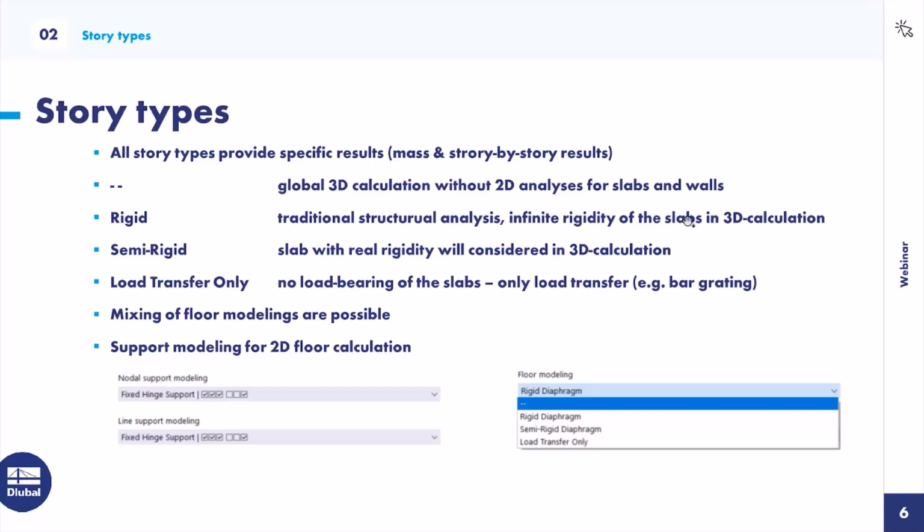Here the slabs get infinite rigidity, and the calculations between walls and slabs are separated, and the results are only an addition of these calculations, I would say.